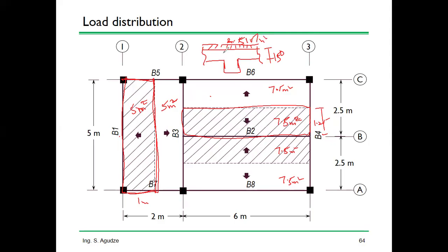So, to make life simple, we take the slab across the beam, even though we know the beam should have been measured from here all the way to here, 450. But if you take the self-weight of the slab, you take everything across so that if you are dealing with the extra load for the beam, it's just this small part remaining.